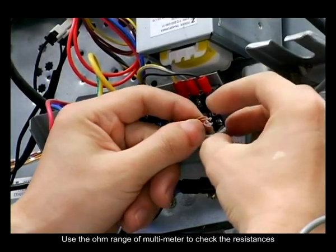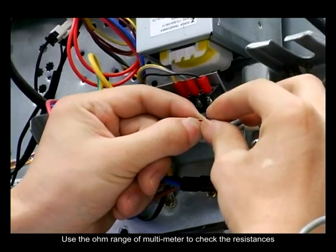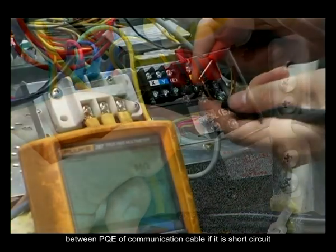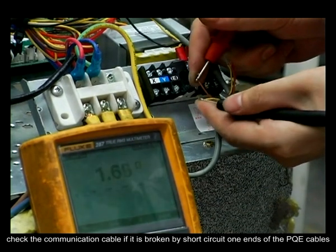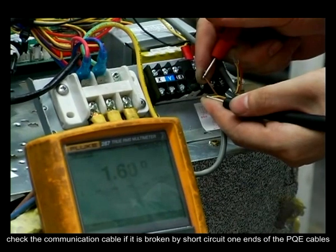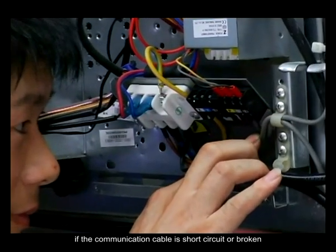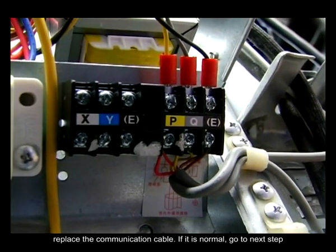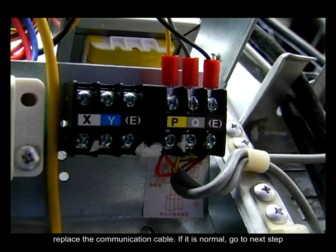Use the ohm range of the multimeter to check the resistance between P, Q, E of the communication cable to see if it is short circuited. Check if the communication cable is broken or short circuited at both ends of the PQE cable. If the communication cable is short circuit or broken, replace the communication cable. If it is normal, go to the next step.